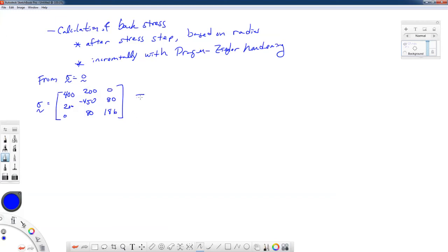And what we did is we converted this to deviatoric stresses. The formula for that is sigma ij minus 1/3 sigma kk Kronecker delta ij, where we have the implied summation with this double subscript here. Alright, so we did that, and we expressed this in stress space. In stress space, the yield criterion takes the form of a circle, or a hypersphere, actually, in 9-dimensional stress space.